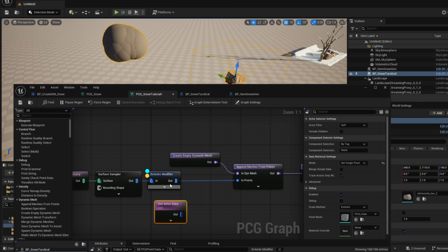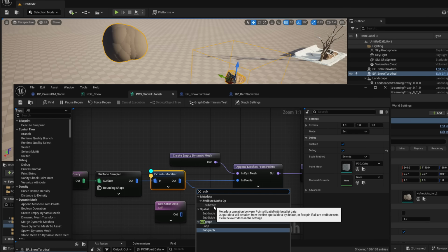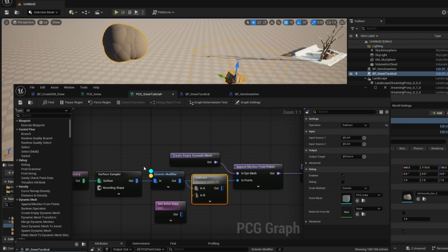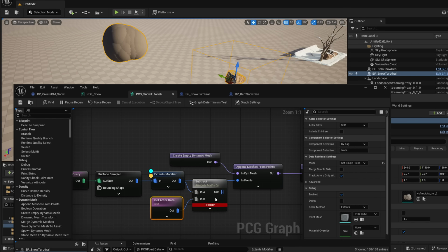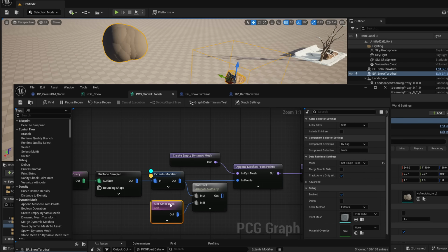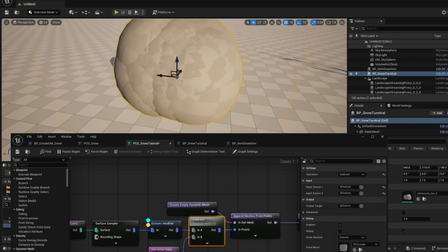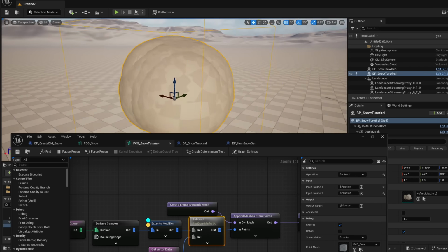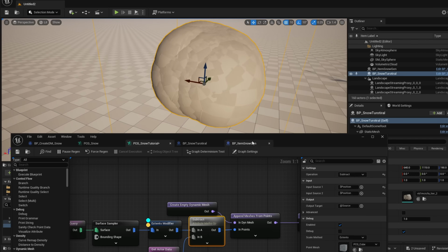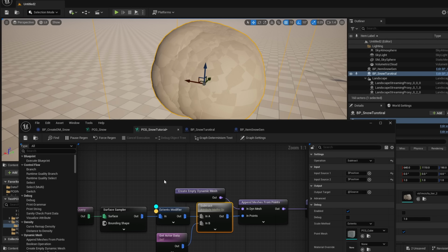of our current actor. So let's do a subtract node after our points generation and connect our actor data. And into the subtract, we'll use the position value for both inputs. So we'll subtract the position of our actor from the position of every point, and then we'll connect it to this in points. And you can now see that these points are generated on top of our boulder. They are very big. So the problem is that this sphere is huge for snow generation.